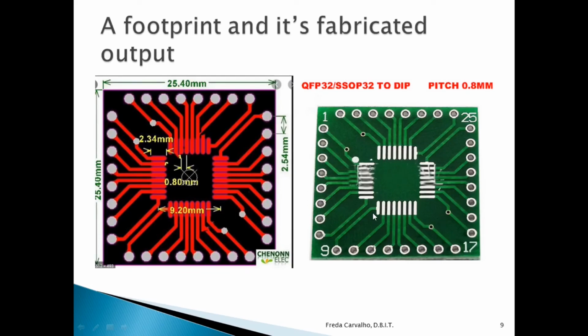So the component has a packaging style, namely QFP32. That is shown to the right, and its corresponding footprint that you are going to use on the PCB making tool of KiCad is to the left, where you can see the footprint is the pattern, which is an exact replica of what is going to happen when the board is etched. So you're going to deal with footprints all depending upon the package style. You need to check the component packaging style that you are going to use, and the footprint has to be accordingly selected while making the layout.